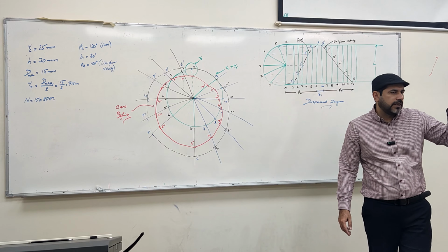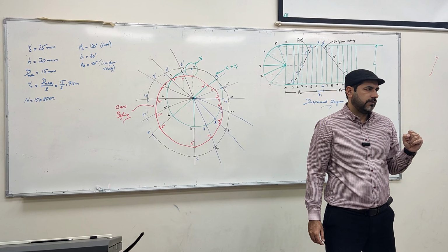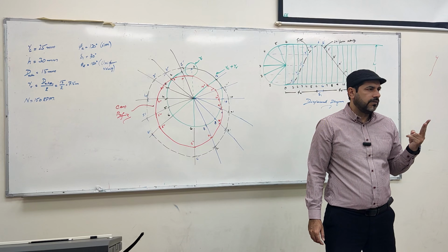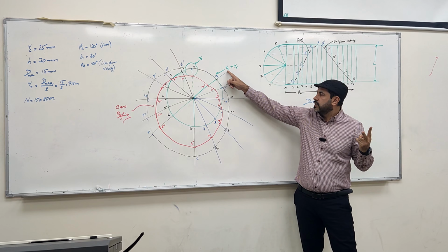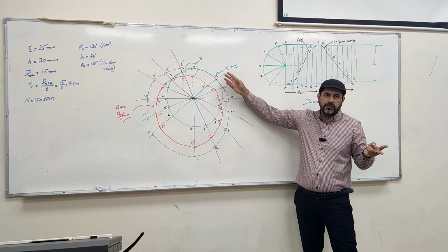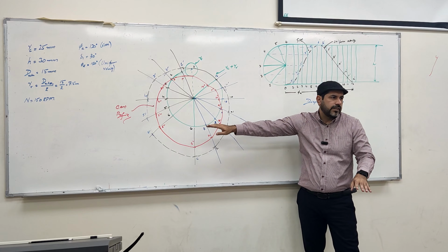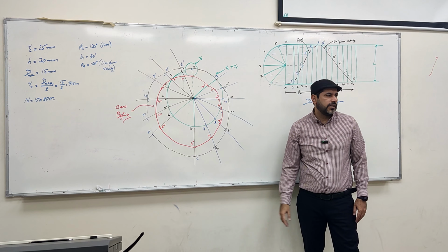Again, a point contact, but in the form of the roller. So two things. The first thing is the base circle you draw in this one is RC plus RR. And just because you add it, at the end you just offset it again. That's the difference between case 1 and this case.